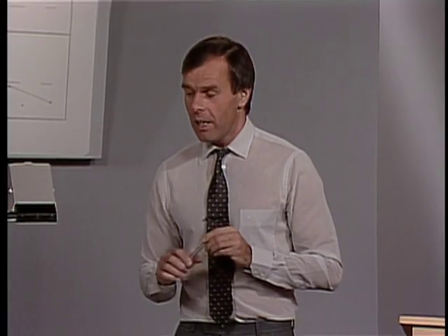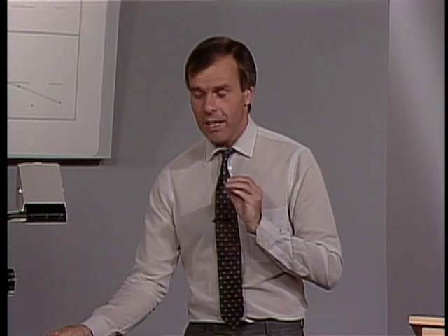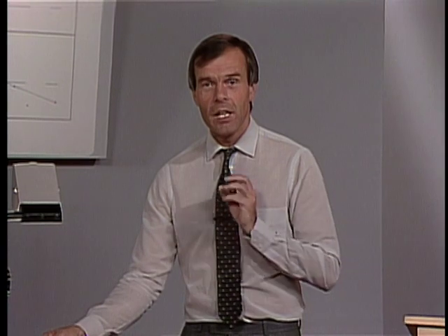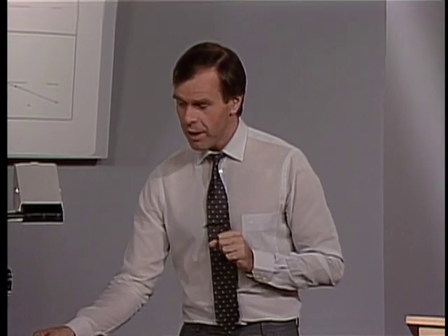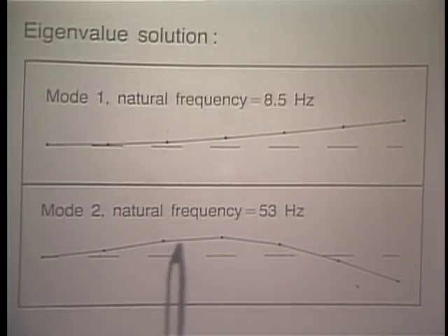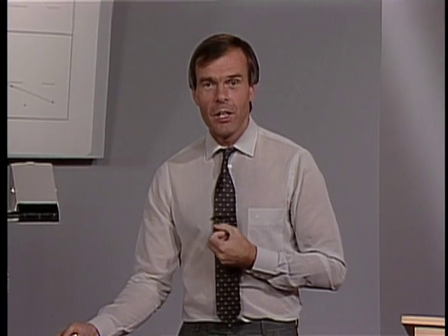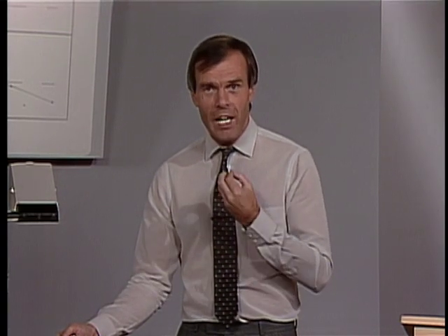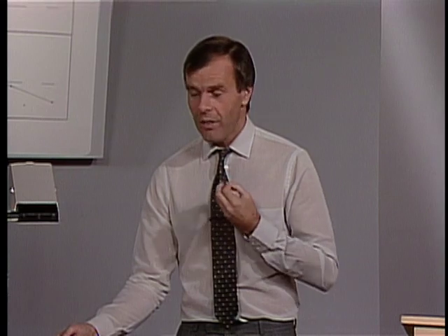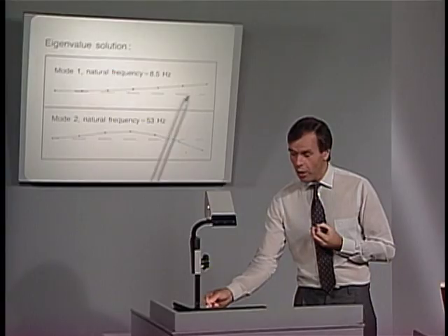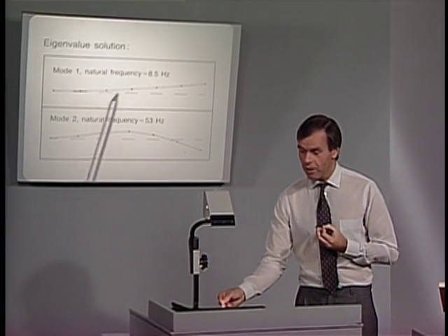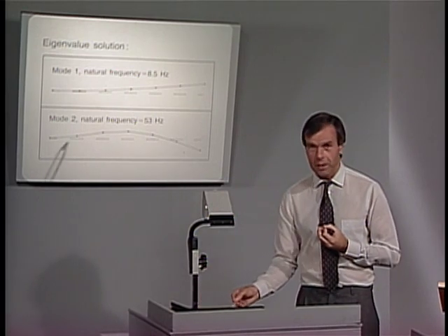However, what we are saying is that we believe we can capture the elastoplastic response of the pipe approximately by using this mode shape and that mode shape as generalized displacement patterns to represent the total pipe response. Of course, there are the heavy approximations that we reduce all of the pipe degrees of freedom to just 2 generalized degrees of freedom.